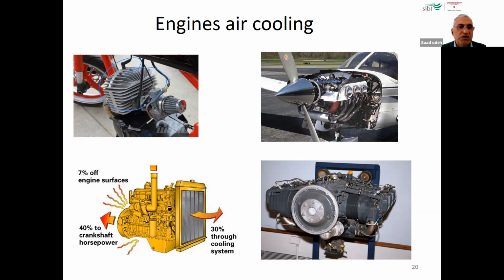Because in a motorbike, using water is going to be very complicated. We could put a radiator in the motorbike with cooling water there, but I need the pump. It's going to make the motorbike bigger. We don't want big. We want a small size of engine. And that's why you can see here it's air cooling, not water cooling. So this is another type of application at bigger scale. Right. Any question? All right.